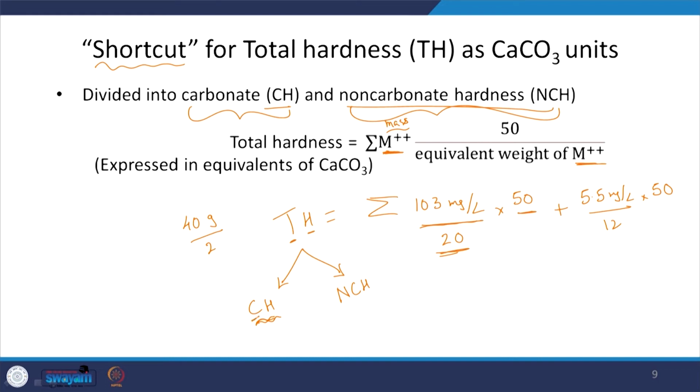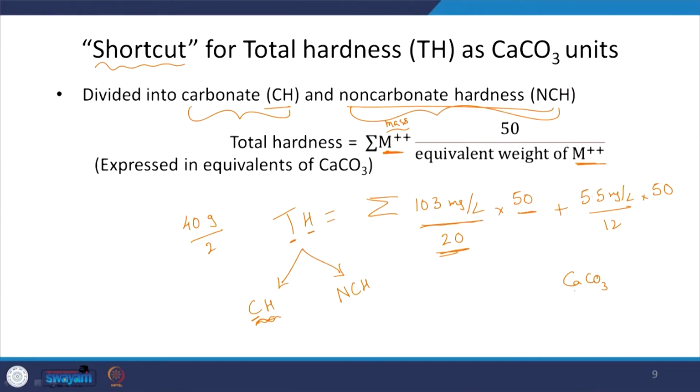but again we are saying carbonate hardness, we will look at why, or maybe I should explain it now. The carbonate hardness, the concern is that, as you saw earlier, we can precipitate out calcium, and one of the forms calcium precipitates out in is CaCO3, right. And what is this going to be dependent upon? If I have Ca2+, how can I go from Ca2+ to CaCO3? What is the other compound that is missing? So, I need to add CO3 2-, right, or need to have CO3 2-. So, if I have enough CO3 2-, by increasing the CO3 2- concentration or Ca2+ concentration, I can go to the right and precipitate out the solid.